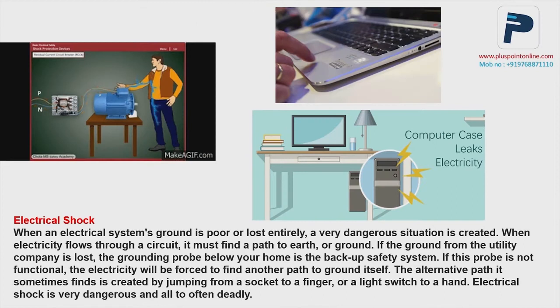Apart from this, when you are working in factories or at home and you have a desktop computer at your place, sometimes when you touch the CPU, you experience a shock. In some companies which have motors or delicate equipment, you experience a current while touching these equipment. Sometimes even while using your laptop with a metallic body, you tend to touch it and experience an electrical shock. The reason for all of this is also weak earthing or leakage earthing.